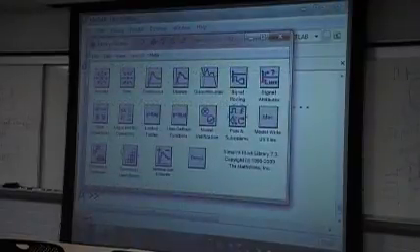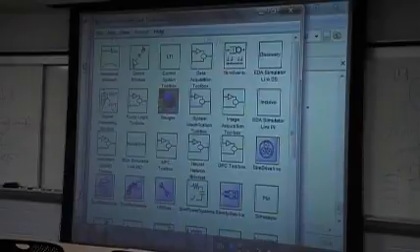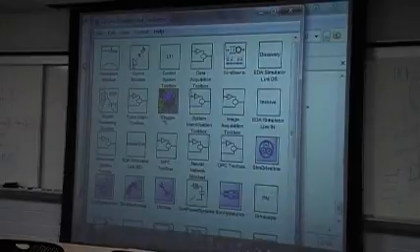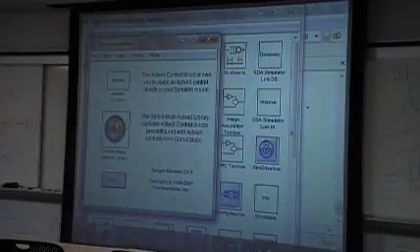If we double click it, then we should have a blockset library like this, and this one is the one that I want to explain, the gauges. We double click it, and we will have displays like this, and in this group there are some useful ActiveX components.